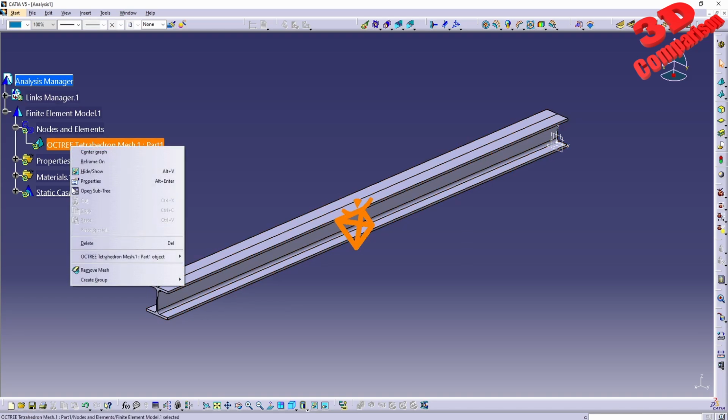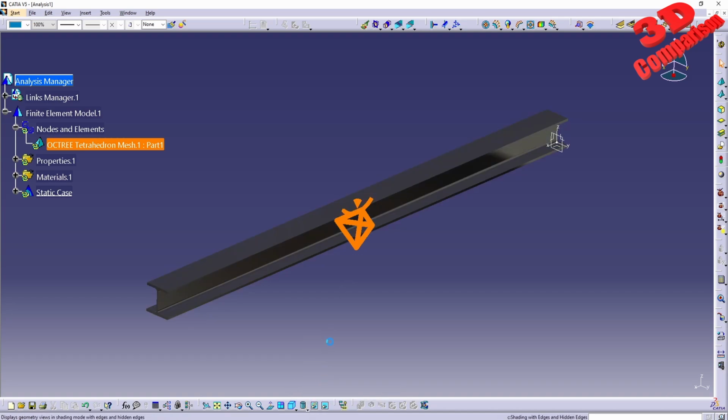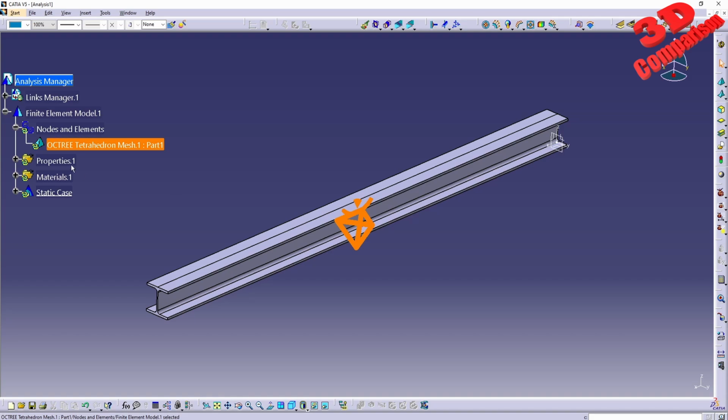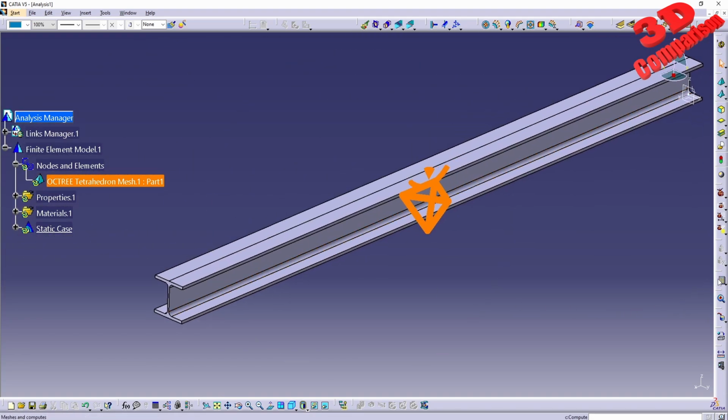We're gonna see that this is waiting for an update over here, but we're gonna be able to see those as soon as we do a computation. So the material is added. Now if I also want to visualize the octree, so how that mesh was divided into those smaller elements that will be used for the analysis, I need to define a compute over here.